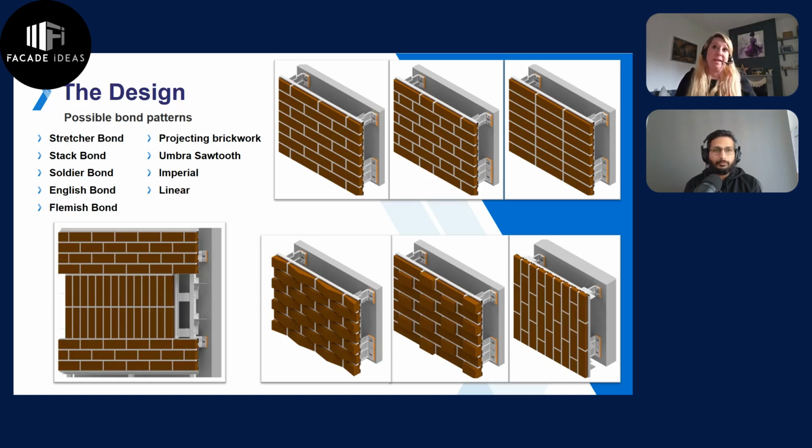What I will say is that with this particular system or with other cladding systems, you would have to cut the brick at certain locations to ensure the grooves were sufficient to be held in place for the system. So again, if you've got a quarter closer, so you've got an English or Flemish bond where we need that, it's again collaborating to understand the principles of it, so that we can ensure those bricks are properly cut and grooved.